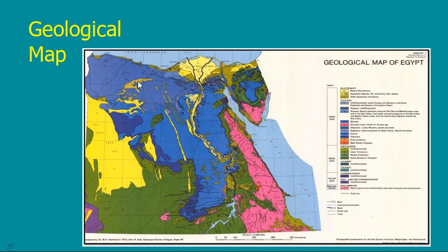If I perform the site investigation and it confirms what I expect, then it is okay, this is fine with me. If there is a contradiction, then I will have to increase my site investigation a little bit, add more boreholes, take more samples, so that I can prove that the formation is okay.